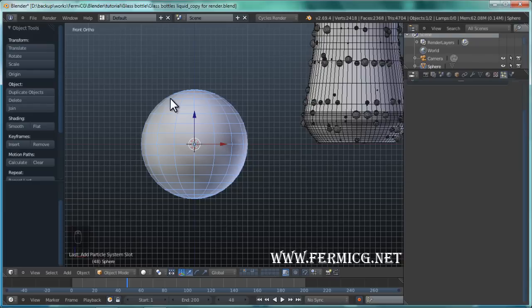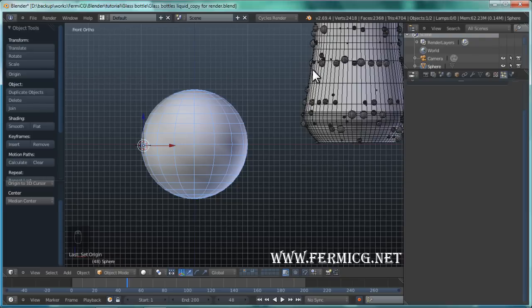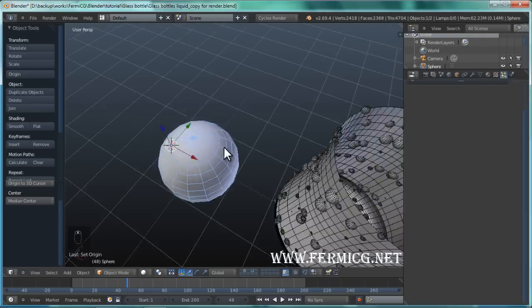to the outer. I just told you that all the dynamic objects, or instance objects, are calculated based on the x-axis. So we need to move this pivot or the origin to the minus x-axis. In order to get that, just move this 3D cursor to here. I'm just using my mouse option. Click here, just like this, and use origin to 3D cursor. So something happened here, we can see what's happening.